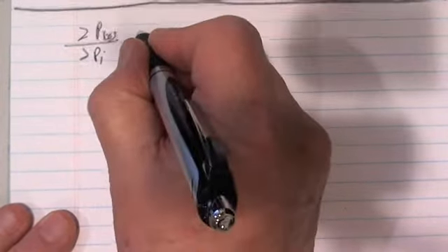Furthermore, if dP loss dPi is less than 0, which can happen, and it just depends on the loading, it means I load the generator up and increase the output, other generators decrease, and the overall effect is that losses go down.